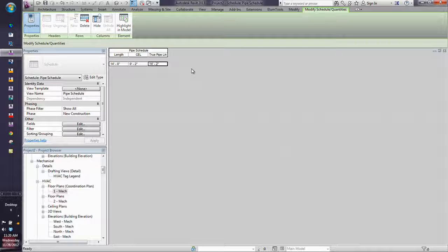You can if you do an associated parameter and you do it as a shared parameter, yeah. But if you have multiple parts, then you would do 700 parameters that it may not need because it may not have a heating coil. Yeah, I actually, stop and talk to me in a minute. I got some on coils I can show you that'll help you in one of our families that we were working on. I'll show you how we actually handled that with a formula instead.